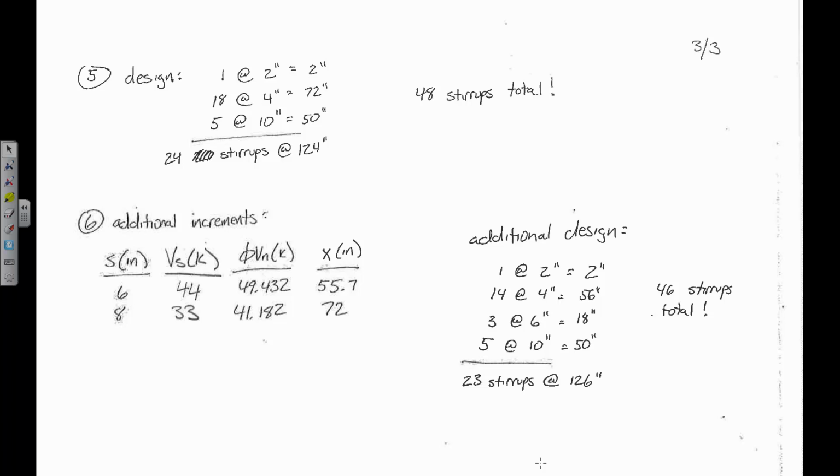By doing that, we were able to shave about 2 stirrups off the beam. Not a lot, but we did trim it down a bit. But there's a point where you could use all these different increments of stirrup spacing and you really aren't going to generate overall economy. There's a point where it just stops mattering.